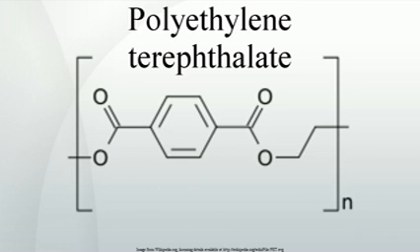Depending on its processing and thermal history, polyethylene terephthalate may exist both as an amorphous, transparent, and as a semi-crystalline polymer. The semi-crystalline material might appear transparent, particle size less than 500 nanometers, or opaque and white, particle size up to a few microns, depending on its crystal structure and particle size.